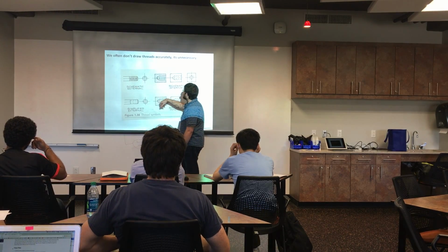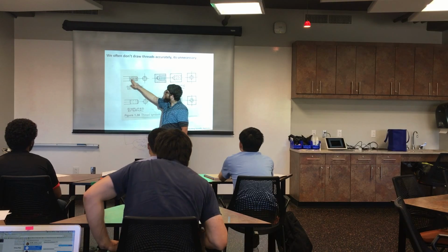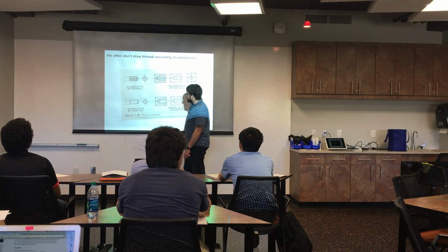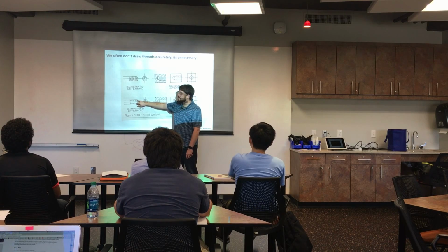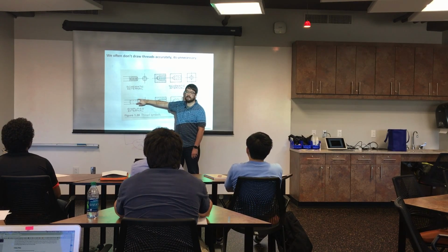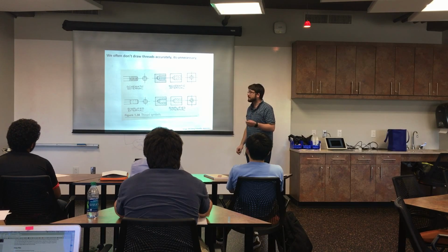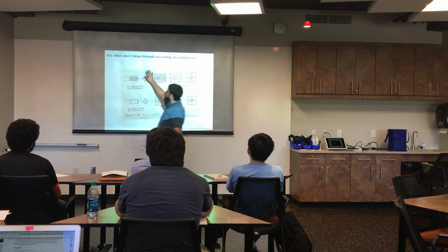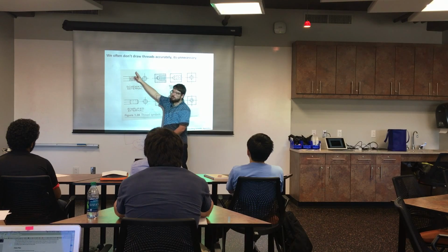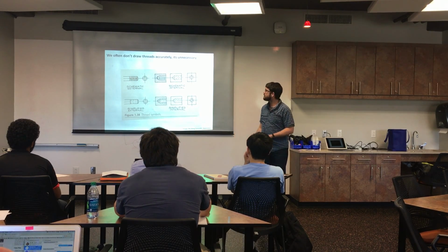We can use these crossed lines like that, so we've got a long line, a short line, a long line, a short line. You can even just use a line like the hidden line to specify the inner diameter of the thread, and then you have the outer diameter of the thread. It's really all you need to do, and then you notate what the thread is. So you would put a note on here, and you would say this is 1/4x20 UNC thread.